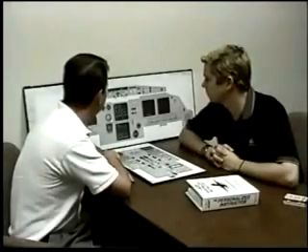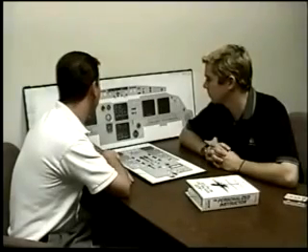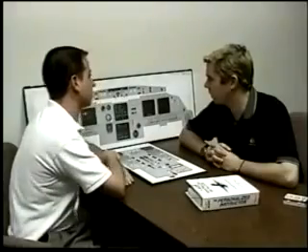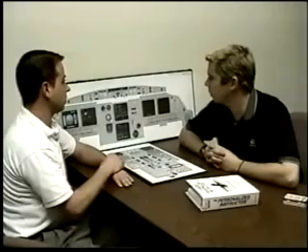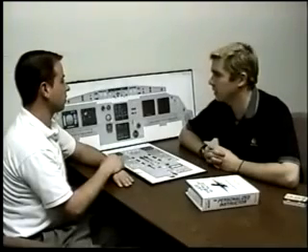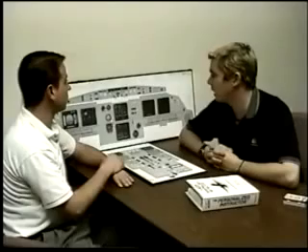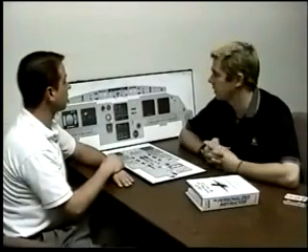Brakes. What are some brake temperatures that you're looking for before takeoff or even taxi in? Before takeoff, the maximum for takeoff is 300 degrees. On taxi in, we're looking for 3 different ones: 60, 150, and 600. 60 degrees is on any brake, we need to have 60 degrees. If it isn't, then the puck never engaged.